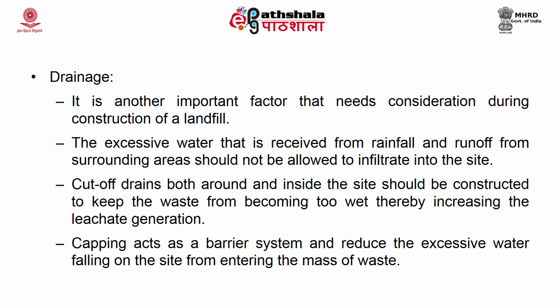Drainage is another important factor that needs to be constructed while you construct a landfill. You should avoid the water from rainfall infiltrating into the waste, because when it enters, obviously it will mix with the leachate and result in the generation of more leachate, which will infiltrate. So, that has to be avoided. This can be avoided by constructing cut off drains both around and inside the site, so that the water can be drained off and the waste will not be wet.